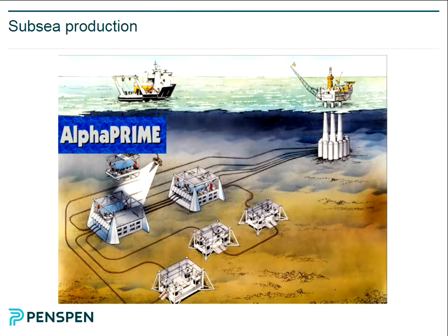The frictional component has a thing called a friction factor in it, F. So it's a friction factor by the density multiplied by the velocity of the fluid squared divided by twice the diameter multiplied by the length. That's known as the Darcy-Weisbach equation. I'm sure it'll be familiar to some of you. It's a classic; you can derive it from the steady flow energy equation.